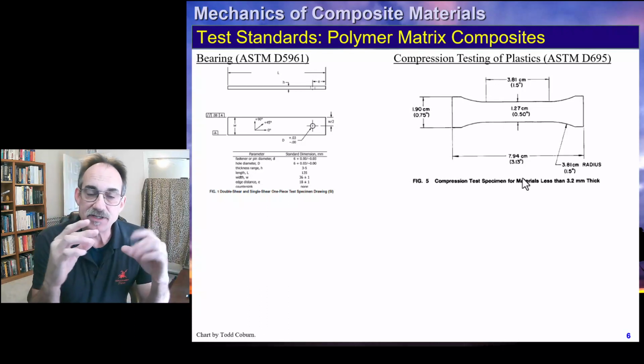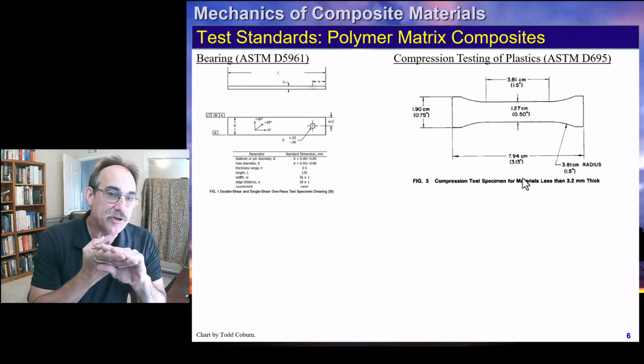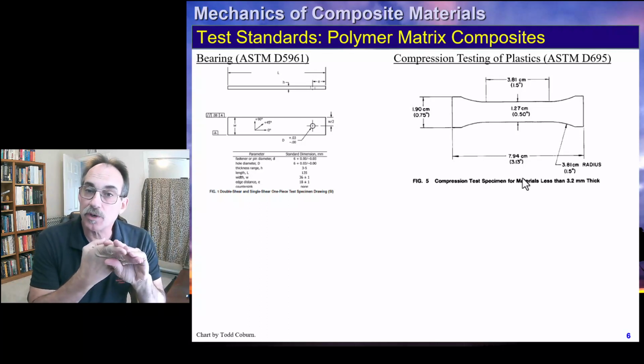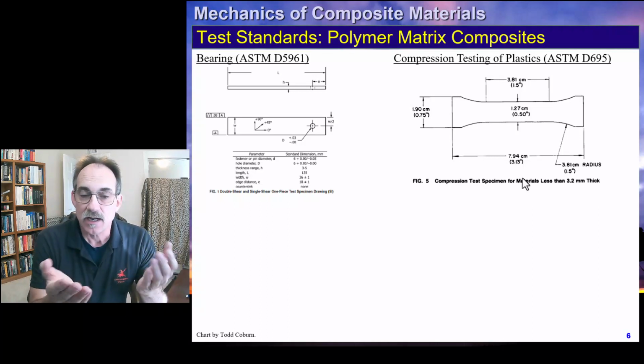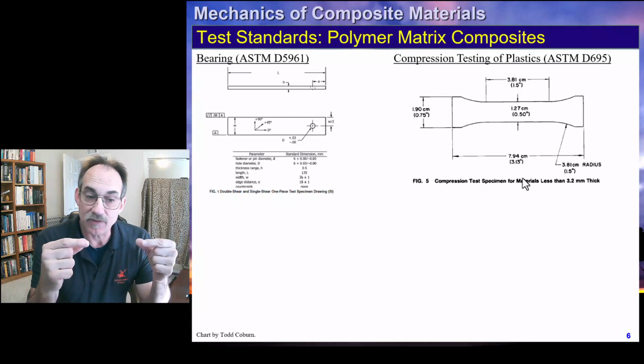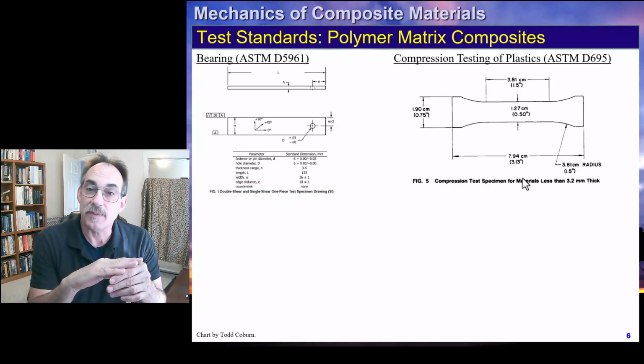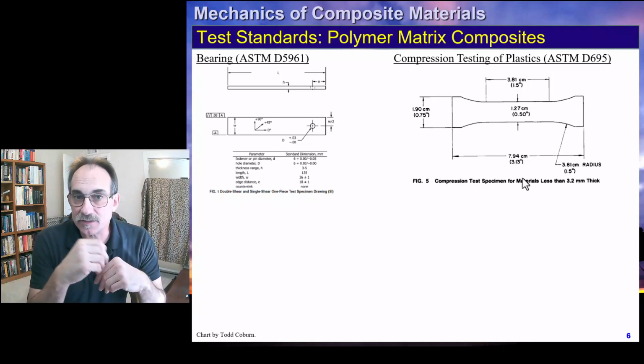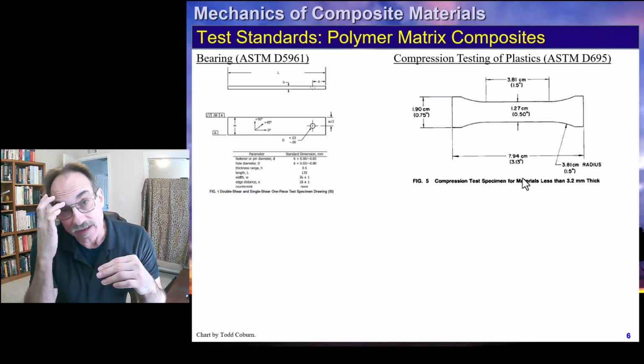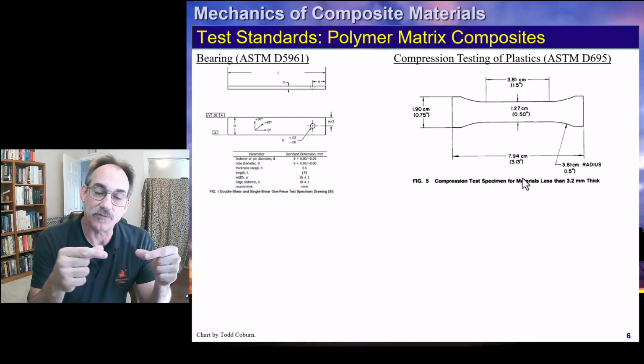This is a shaped sample I have used in the past, especially when characterizing defects. We would cut little samples out of the area that was shown by the ultrasound to be good material or to meet expectations or requirements. And then out of the material that had defects, we'd cut little flat samples.